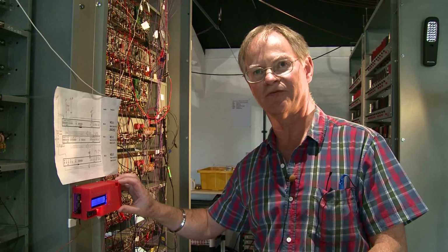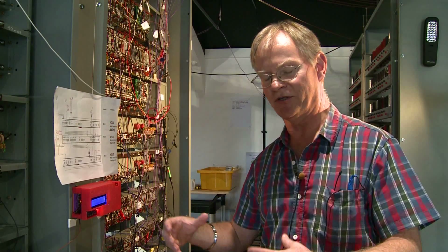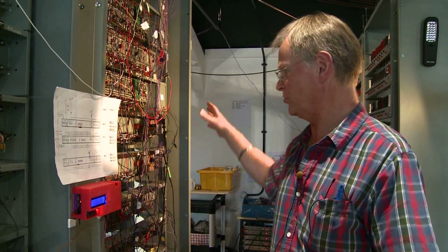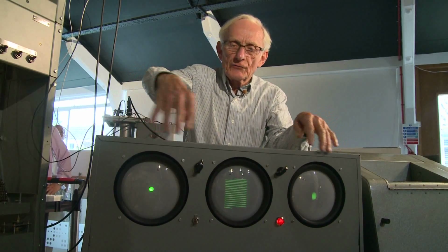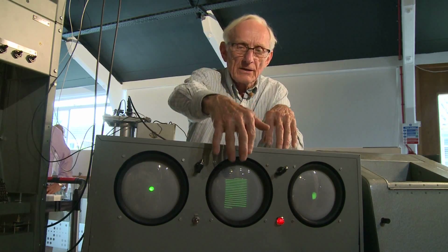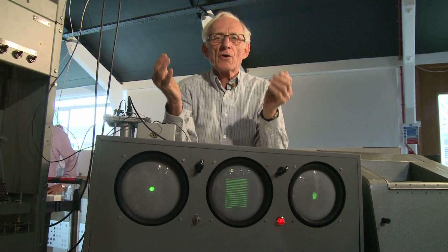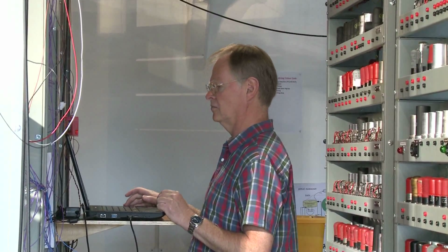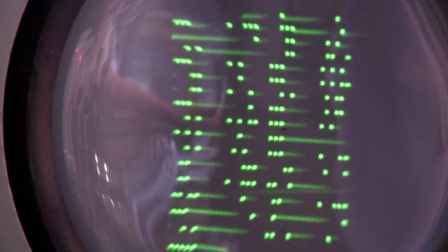This particular test box that we have is dedicated to generating the program sequences that go into the tanks or delay lines. That's the data Chris can see on the VDUs. You can see the 3 cathode ray tubes displaying certain registers, but in particular this central tube is showing the contents of one of the memory tanks. At the moment that one is empty, and using Tom's signal sequence injector we can load a program into that memory tank, and in this case it's part of the initial orders, and if Tom can now inject, we should see the program has appeared in the tank and displayed on this tube here.